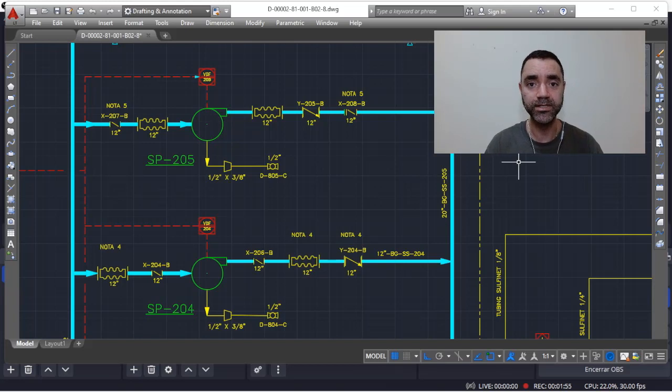And here you can see a sheet for a piping and instrumentation diagram, also with process data sheets at a minimum. The process data sheet is the document that has the results of your heat and material balance, to purchase or to forward to other disciplines for specification, and after that purchase the equipment, control valves, pressure relief devices,